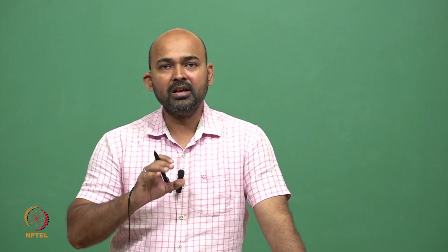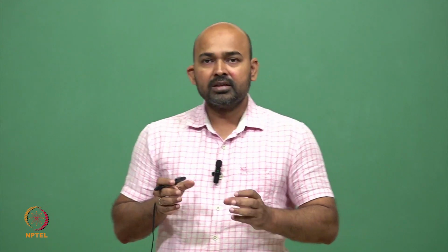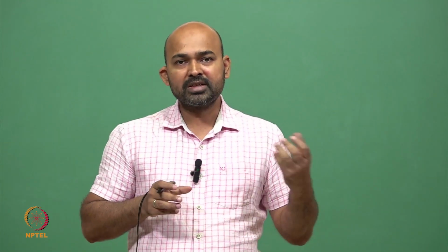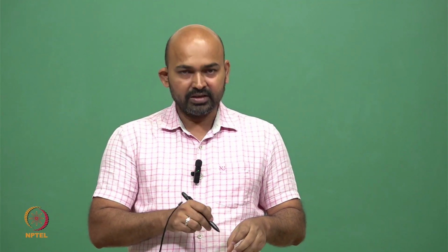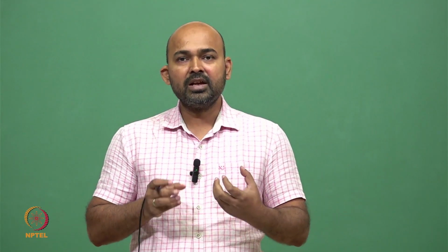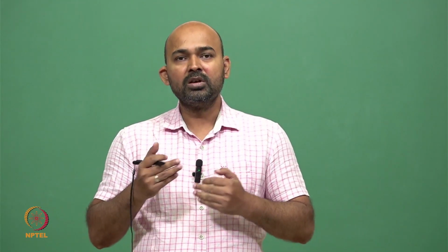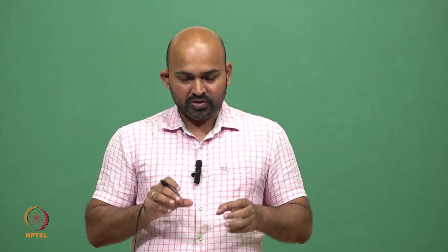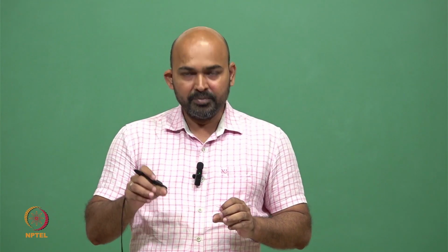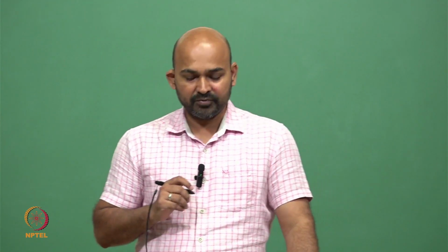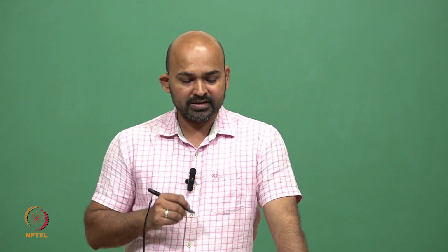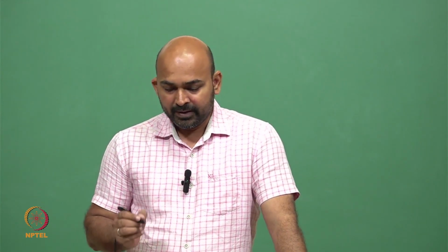We apply the signal and the signal will be read out by a separate sensor, which in this case is this radar. This will gather that information and will decode the information. The SAW sensor is used as a medium to gather that information. So here it is acting as an indirect SAW sensor.